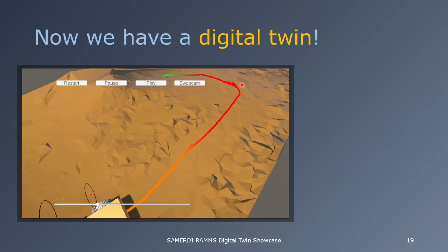And then eventually it got itself unstuck, came around the corner, and stuff dried out and got a bit more flat. And then the motion resistance assumes a much more neutral value, the orange. So not only did we get traction estimates from this process, we also got motion resistance estimates, which are also useful to the operator for interpreting how this vehicle is experiencing the terrain.